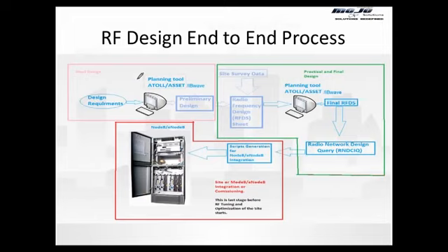when that design, which was an ideal design, has to be implemented. If the ideal design said the height of the site is 30 meters, but actually when you go to a site, it's on a rooftop, and you cannot install a tower, and it's 15 meters. Then you have to adjust the site. You have to accept it, reject it, or adapt to the site requirement. So you have to actually redesign the whole site and fit it according to the site. Then you do a detailed survey and tell what is possible or not possible.